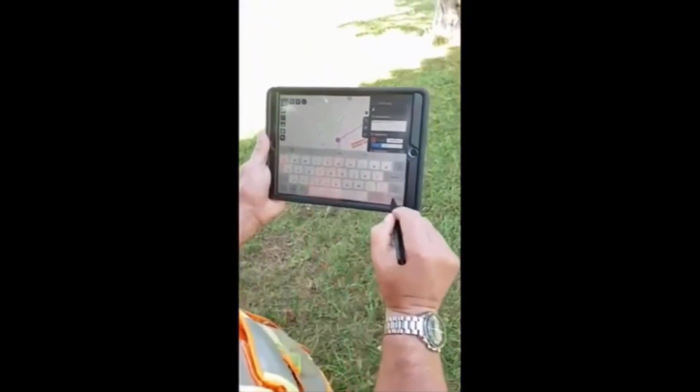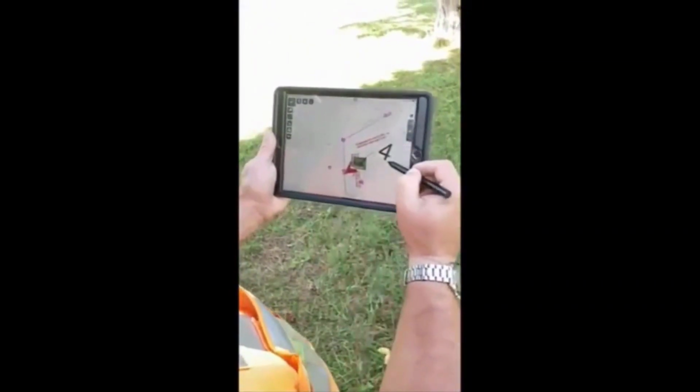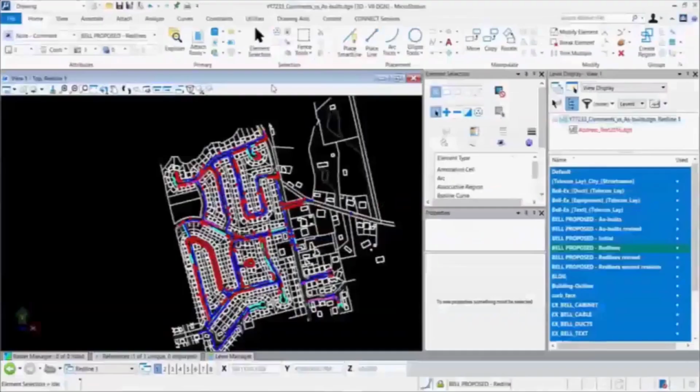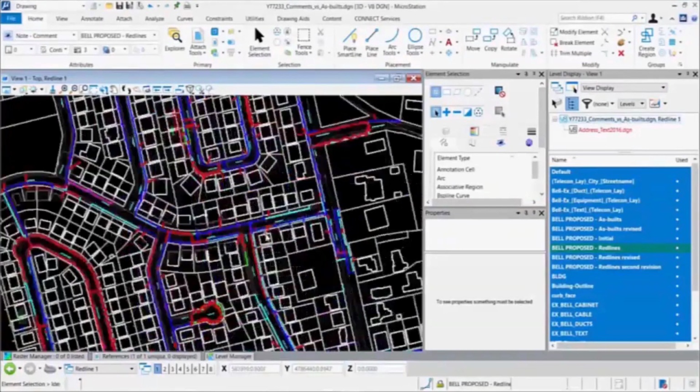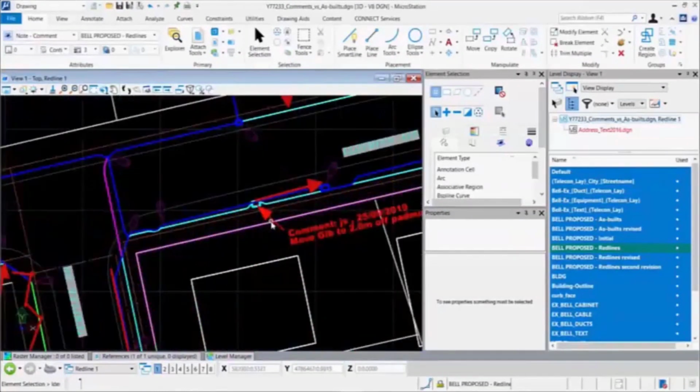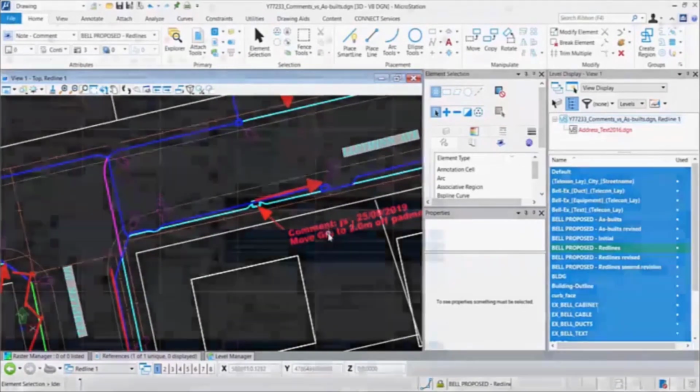Using Bentley mobile application, the city project team is able to document written notes, markups, photos, and video. All notes and feedback is geospatially referenced for seamless transmission back to an office environment. Field comments are brought back into the office through the iCloud for review. Here we are able to see the background files, proposed design, office comments, construction notes, and as-built submissions all in one. Any discrepancies between records are flagged and further.